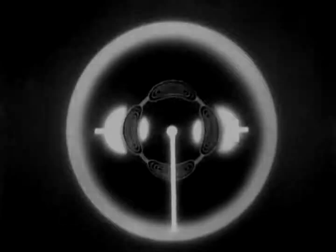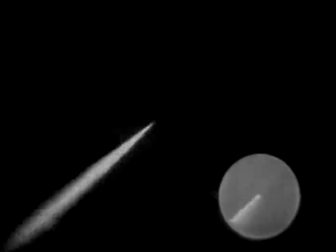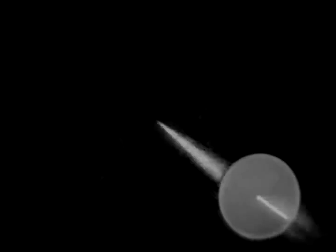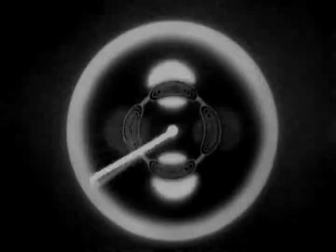Same thing is true of the other set of coils. Current flowing through them one way will deflect the baseline upwards. And a change in polarity will deflect the beam downwards. By synchronizing the flow of current through these coils with the antenna, the baseline will always point in the same direction as the antenna. Thus, by altering the flow of current through the four coils, like this, we can rotate the baseline without rotating the coils, which means we can forget about movable parts, bearings, and the added weight that goes with them.